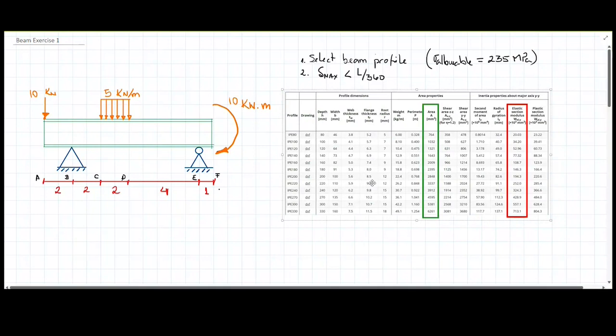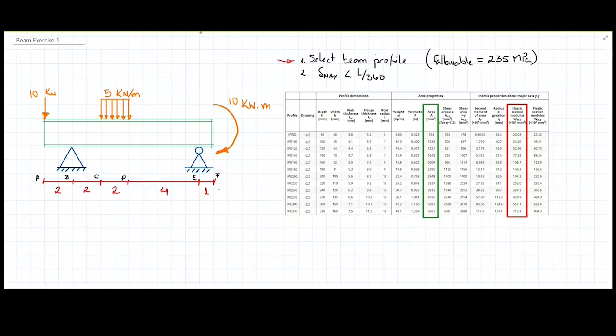Now we have this other restriction, and then the situation that we need to validate: first, that the stress doesn't exceed the allowable stress here, and then the bending. It might be possible that we select a beam, and that beam behaves nicely in the sense that it withstands all the stresses caused by these loads here. However, when we try to calculate the deformation, it is so big that, even though it is selected according to the method we're going to be using here, functionally it's not good according to the deformation it is having. And then you would have to take actions to overcome that fact.